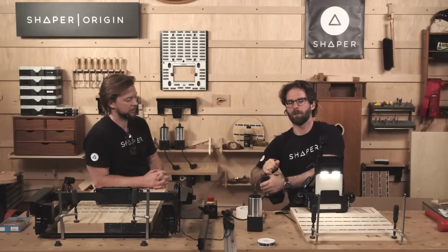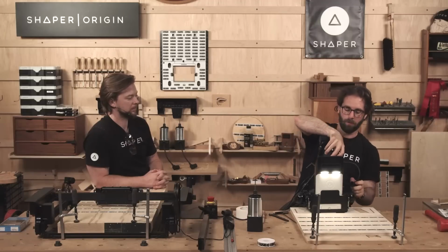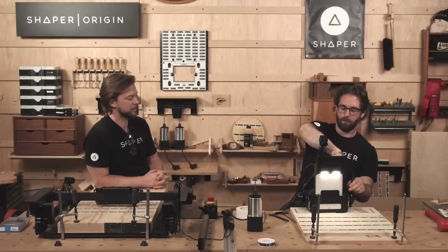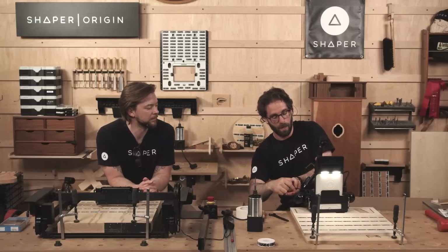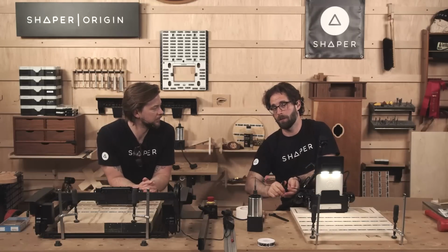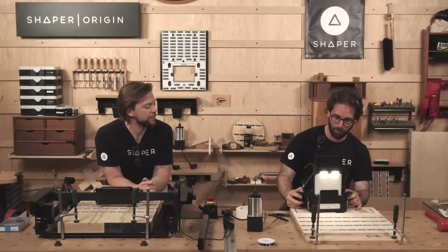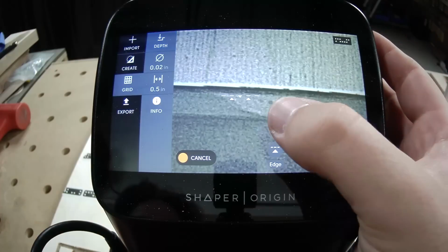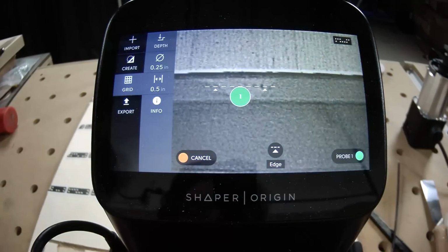And this is pretty similar to all this stuff that we've been doing, where you send it over to Studio, you fix it, or you update your design, and you re-import it right back to where it goes. The difference here just being that, hey, you can make your grid after you place your design instead of before. Yeah. All right, lowering this down so that we get that probing depth. That's much better. Now, we do want to make sure that the router bit diameter is correct.